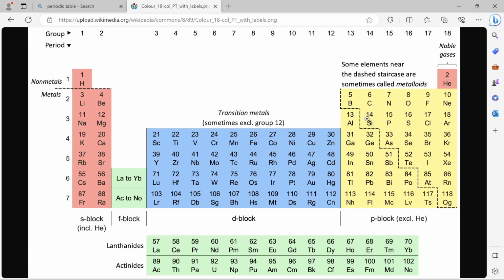So 3 of the silicon electrons will bond with 3 of gallium's electrons. There will be one more silicon bond where there is an absence of an electron from gallium. So there will be 4 bonds, but one of them has an absence of 1 electron, because gallium has only 3 electrons.